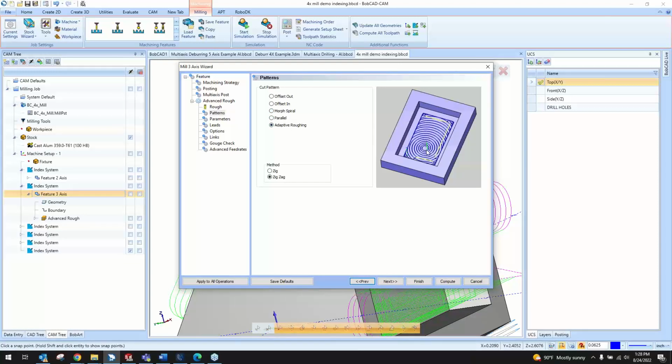The tool will start at the center location, continually spiral its way out, keeping constant tool engagement the whole time. This is our zigzag method, so when it gets to the edges here, it's just going to go back and forth across it, across here, link back, across in the corners, and then the other 2 corners there. Or zig, where if you're just doing one directional cutting, it's going to spiral around. Once it gets to the edges here, it'll have this link in yellow and then going across, link back. And that's a rapid move, also considered trochoidal milling.